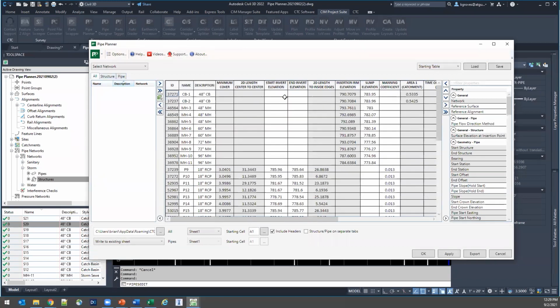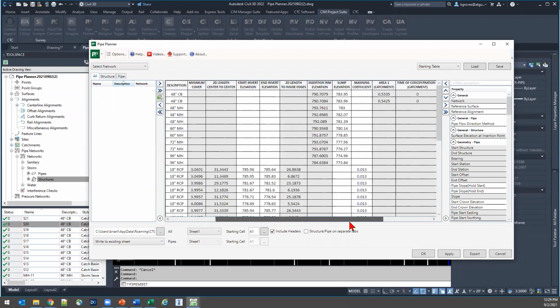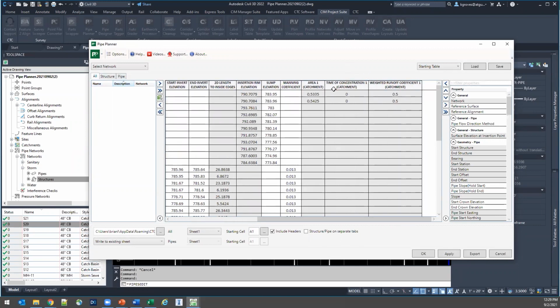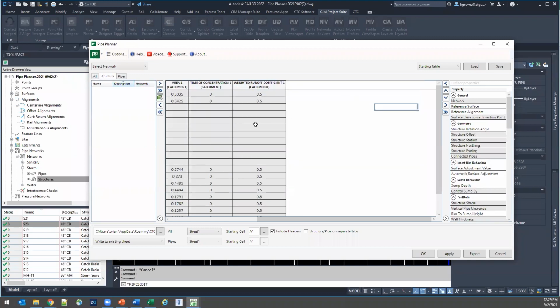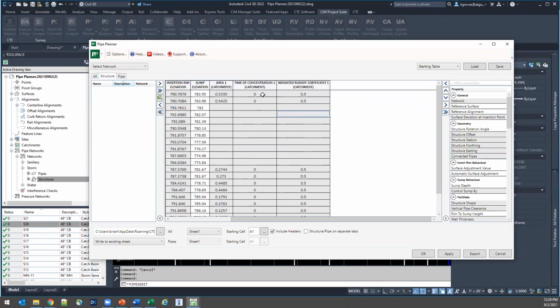And I wanted to mention that I'm in version 22 for a very specific reason. And that is in version 22, Autodesk opened up the API. I forget what the actual acronym stands for, but if you can write code, you can talk to anything that's exposed in the API. It's a little window into the software for different things that you can manipulate or read or do math on. In version 22, Autodesk opened up our Civil 3D catchment objects to that API. So we can read that now as part of our structure data, as long as we have a Civil 3D catchment mapped to that structure.